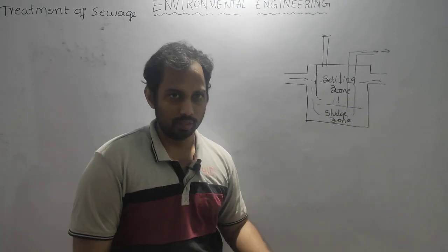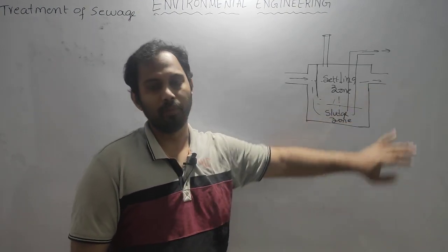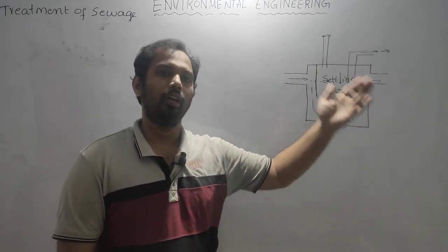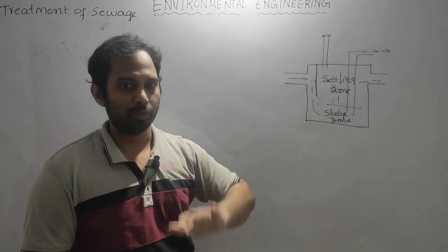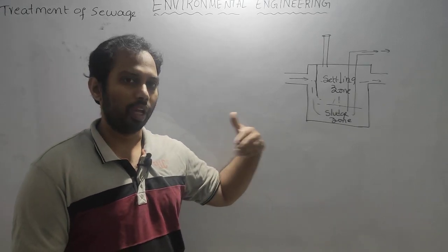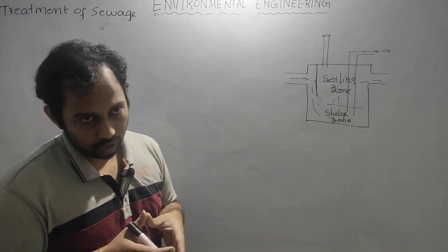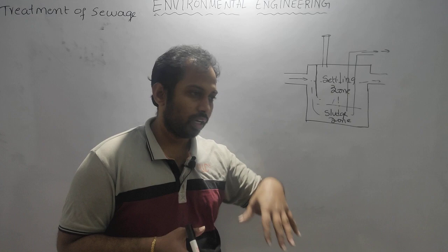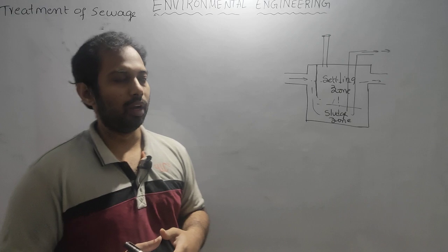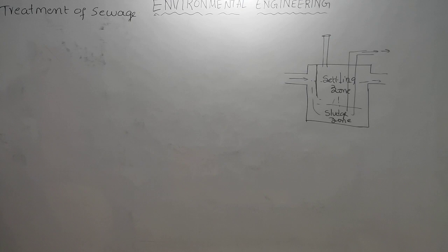In those cases, when the BOD of the effluent coming out of the septic tank is considerable, we will send that effluent onto a soak pit or drain, dispersion trenches or cesspools, leaching cesspools. All these mechanisms are available to take care of the effluent. So the septic tank can be used for household activities, and also for a group of people in a community, depending upon the drainage availability in that locality. This is how the septic tank will work.